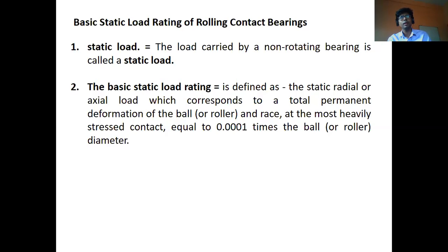Then wear resistance is very important. Another is corrosion resistance. Another is fatigue, because the bearing is used for a long time, so after some time there is a chance of fatigue failure on the ball. Fatigue failure is mostly due to the static load.